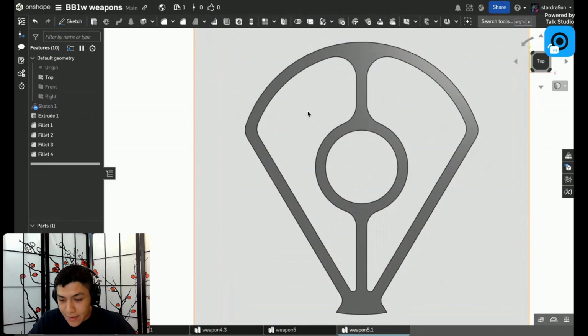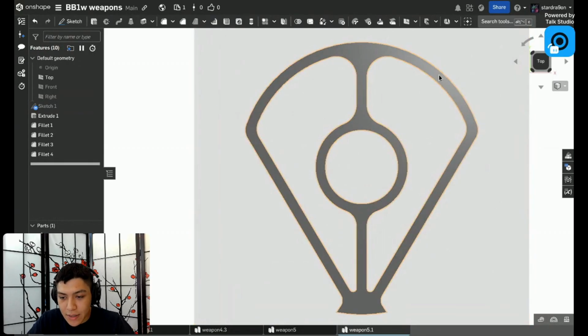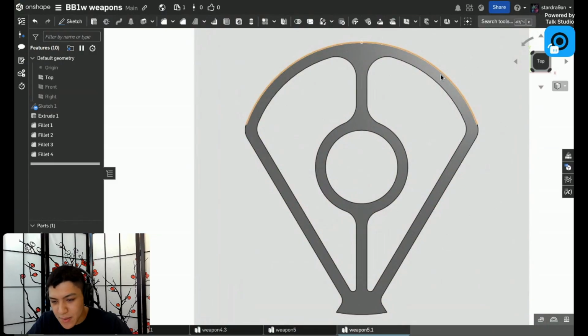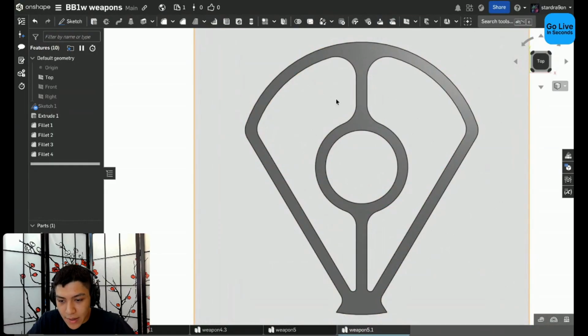Now, I know for a fact that I have about 92 grams available, and it's always wise to take off 1 or 2 grams to make sure that there is a cushion, so in case you do need to make a very small change to something, maybe your electronics, it won't affect you, and also for any scale inaccuracies. So I actually have 93 grams available, but I'm going with 92 to make sure that I am safe.